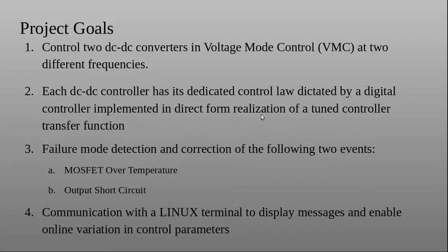So coming to the project goals, we are trying to control two DC-DC converters in voltage mode control. This is one of the types of control schemes used in power electronics for DC-DC converters, and each DC-DC controller has its dedicated control law dictated by a digital controller implemented in direct form realization of a tuned controller transfer function. This transfer function is designed in MATLAB and is out of the scope of this course, but has been designed previously, and without which this project wouldn't have been possible.